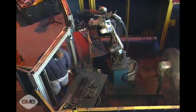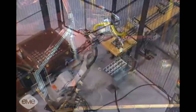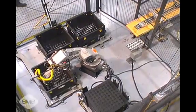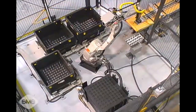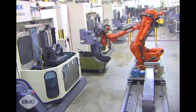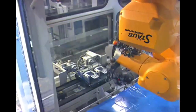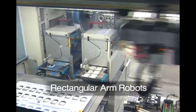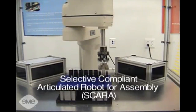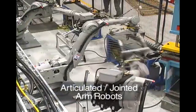Another important characteristic of an industrial robot is its work envelope. This represents the robot's maximum reach in all directions. It varies with the robot's configuration and overall size. Industrial robots are generally classified on the basis of their arm's geometric configuration, with the primary types including rectangular arm robots, selective compliant articulated robot for assembly or SCARA robots, and articulated or jointed arm robots.